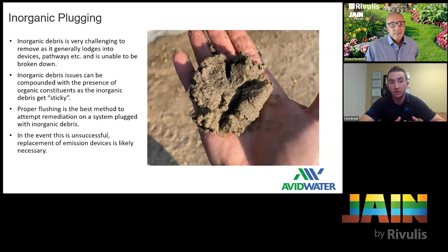One thing that's important to note is inorganic debris can be compounded with the presence of organics. Organics tend to get sticky, they're living, they're films, they're these microbes that we've talked about. And so they get sticky, they grab a piece of sand or silt or clay that otherwise would have gone by, and now that's gotten stuck. Now the next one comes by, but doesn't go, it sticks as well. And then you end up with this compounding effect. Proper flushing is always the best method to attempt remediation on inorganic debris. Hopefully it's stuck on maybe the outside of the emitter.